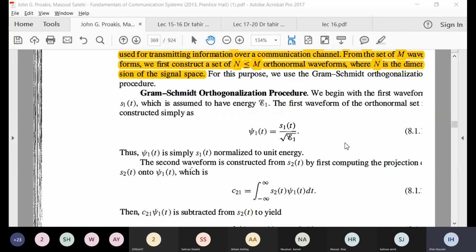But here remember that all those analog signals that you will use to represent our binary modulation signals or our M-ary modulation signals, for instance, 2 signals represent 1 bit, or to represent 2 bits you will have 4 signals. So all these signals are energy signals. They are limited in time, so that you have their finite energy. And once they are limited, you can very well find the energies: find the instantaneous power, x square, integrate, and you will get the energies.